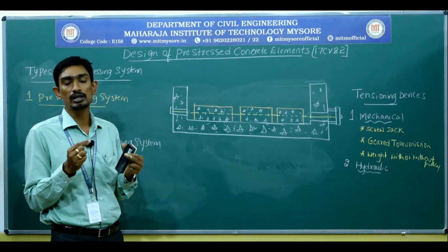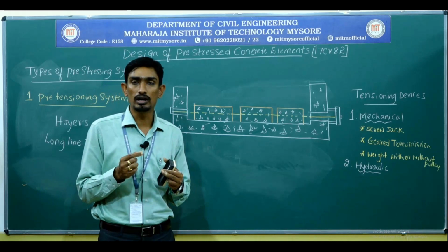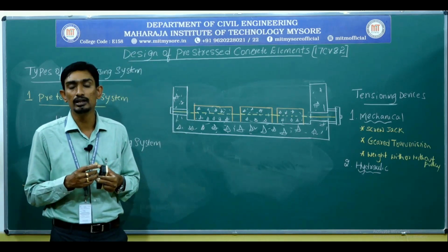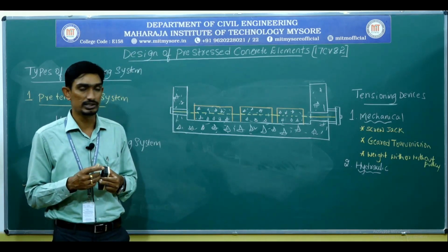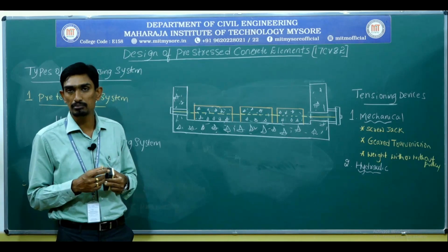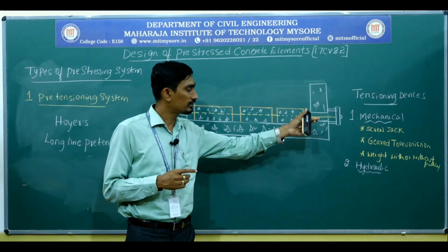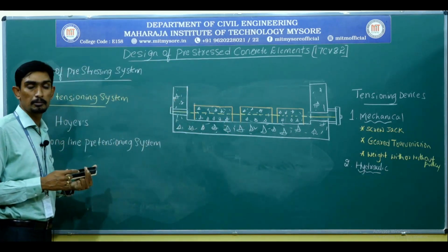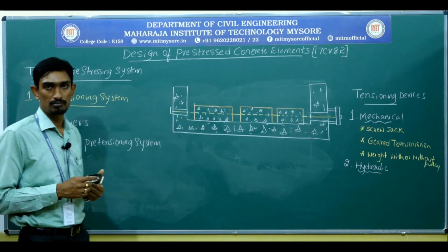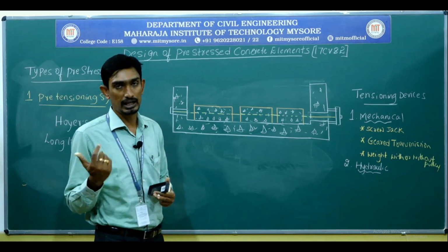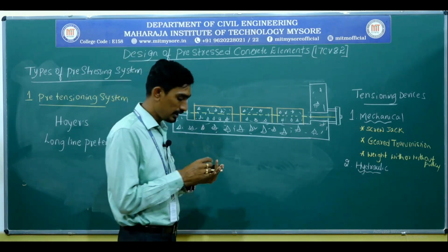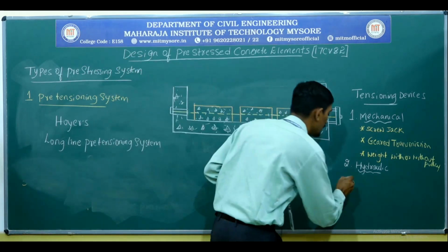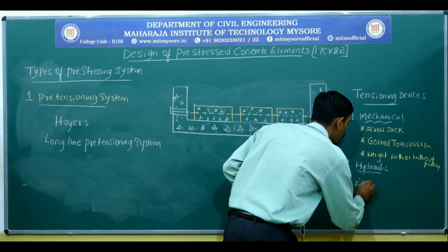Whatever tendon will be embedded in the concrete, that tensioning will be done using this hydraulic jack. And please remember, these devices will also be used for the post-tensioning prestressing system, which I am going to explain next. And the next is the electrical tensioning device.